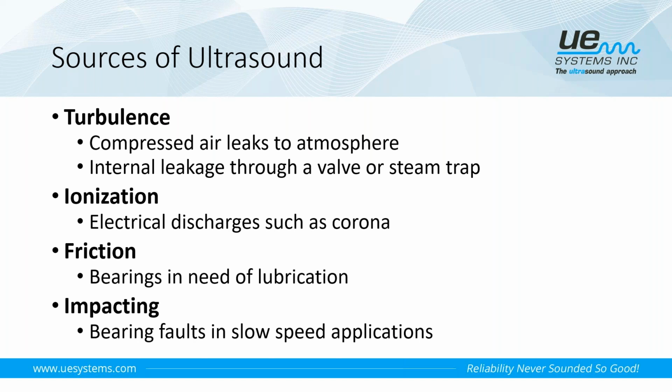Ionization. Primarily we're talking about corona discharge. The definition of corona discharge is actually the ionization of air surrounding an electrical connection above 1,000 volts. The thing about corona, and where we see complementary use of ultrasound and infrared together, is it typically will not produce enough heat to be detectable with a standard infrared camera, but it does produce high frequency sound. So if you're using a combination of ultrasound and infrared together, you're pretty well guaranteed to find just about any kind of fault that may be occurring with your electrical assets.